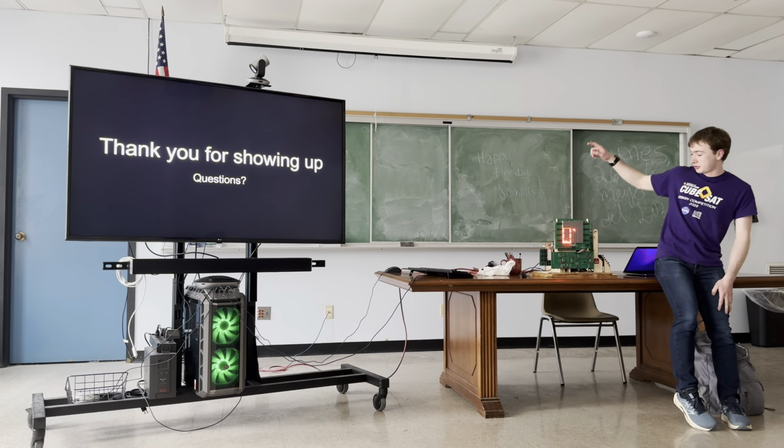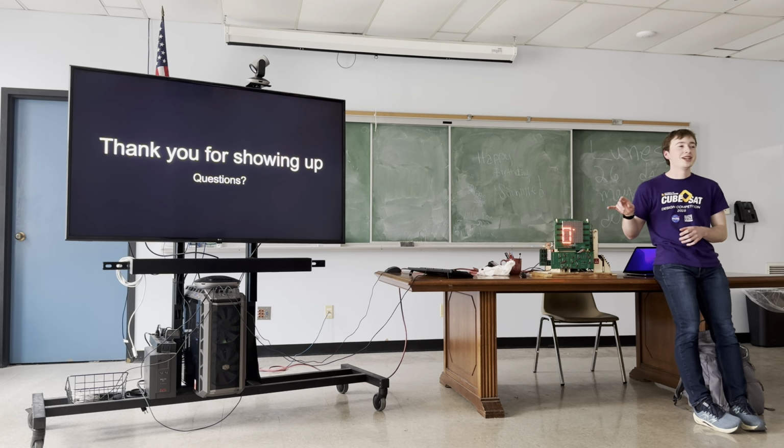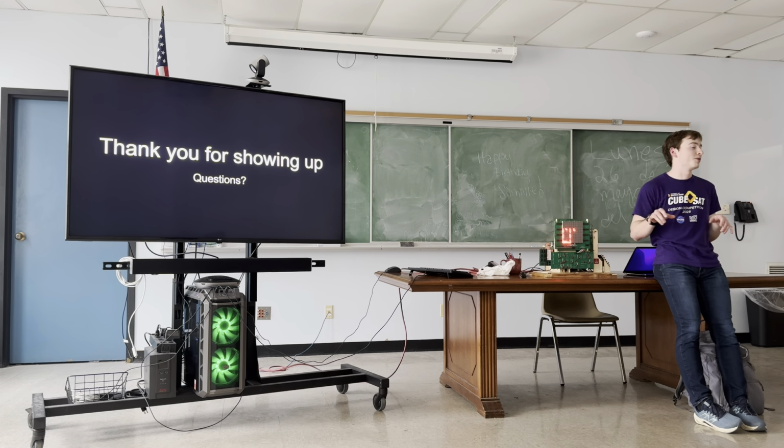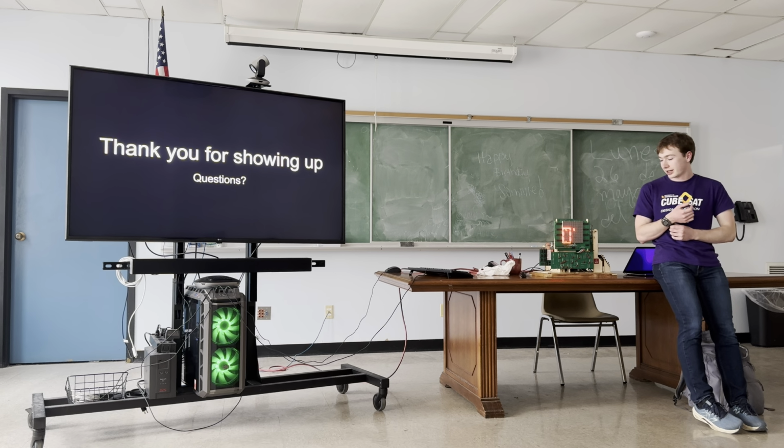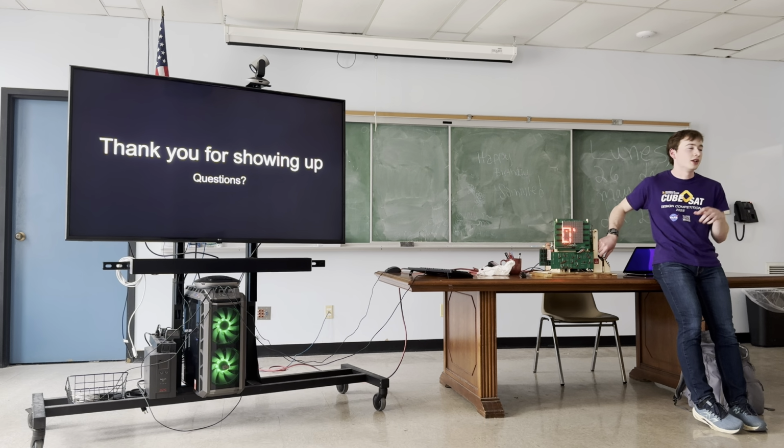I also have to make sure that a wire here is disconnected, otherwise it'll power the whole thing when I turn the Arduino on. And because Tetris was so big, it wouldn't fit in the Arduino's memory because it only has like 2 kilobytes or something. So I have to load it in chunks, but it does work. And I'm too lazy to figure out how to clock it in over serial.